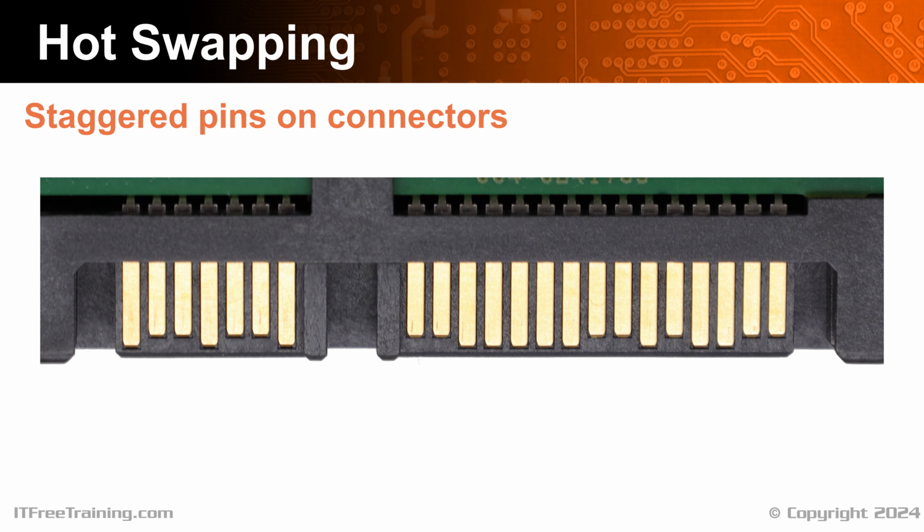SATA facilitates hot swapping at the hardware level, allowing storage devices to be connected and disconnected while the computer is operational. However, there is a risk associated with hot swapping. The risk occurs when the device is plugged in or unplugged, as a power surge occurring during the connection or disconnection could potentially damage the storage device, with the highest risk occurring when the device is initially plugged in.